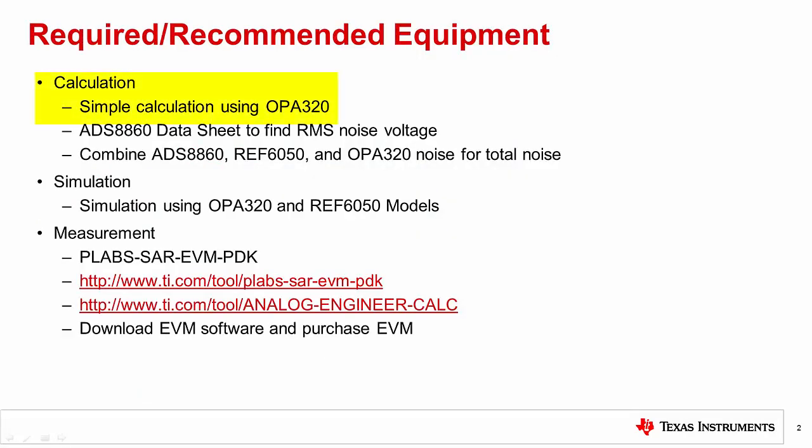For this lab, we will use the OPA320 datasheet to do a total RMS noise hand calculation. Then we will simulate the noise for the same OPA320 circuit using TINASPICE and compare the hand calculation to the simulation. We will also simulate the noise for the REF6050.